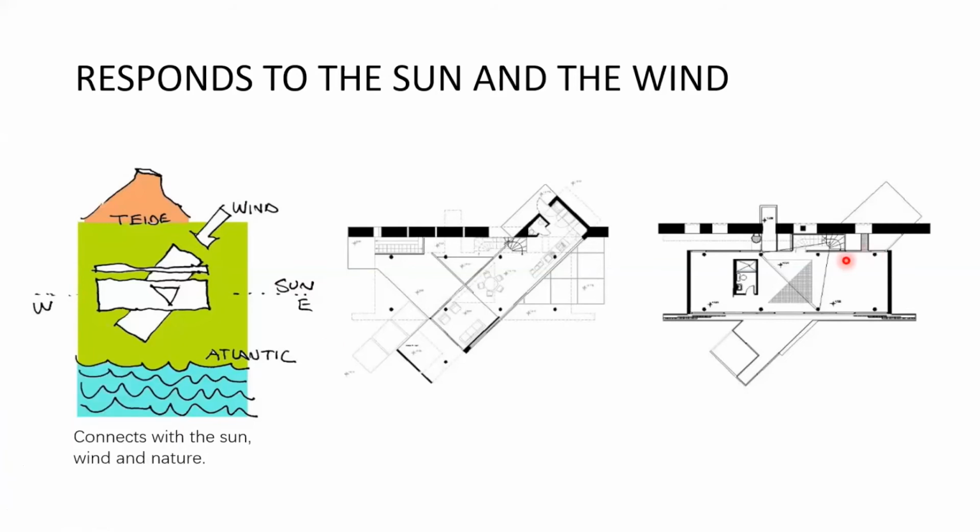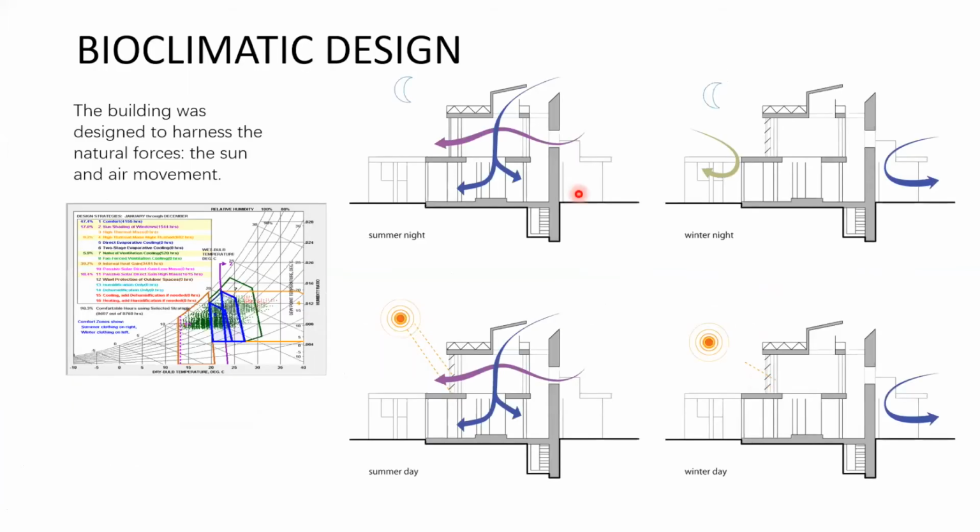And then in the middle, let me just show you here, this area here, there's a wind scoop that passes actually through the space from the outside to the inside. So the air passes through the building, and we can have natural ventilation summer night and summer day, but we can close the building during the winter for ventilation, but we can still provide some passive heating. There's no mechanical heating, no mechanical cooling in this building. You can see again, it's quite close to the comfort zone outside.